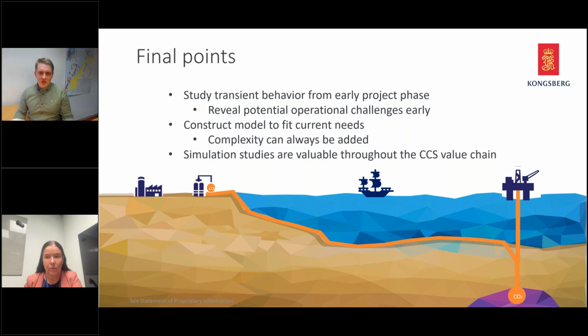So the process simulator actually orchestrates the multiphase simulation. So it sends data back and forth between the two simulators. And I typically say, okay, how important, for instance, is your choke valve? If your choke valve is extremely important to you, you want it incorporated in LedaFlow.